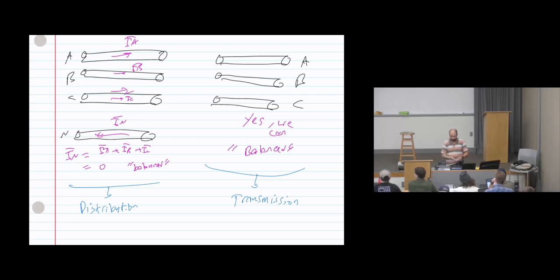While when we are in transmission lines, transmitting the power, for example, from Lagrange to here, it's, I don't know how many miles, but it's a long distance, or from Birmingham to here, whatever, then it will be a very long distance. So when we remove the fourth wire, this will save a lot of money. And even the neutral, it will be meaningless because it's zero. Okay, does this make sense?